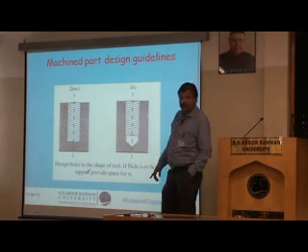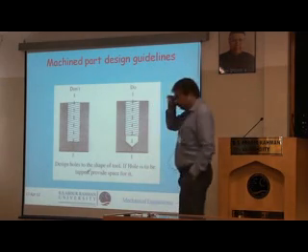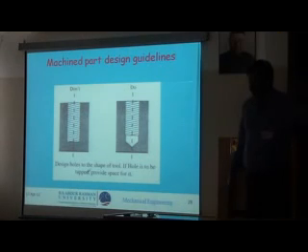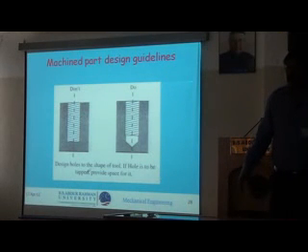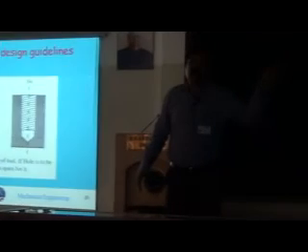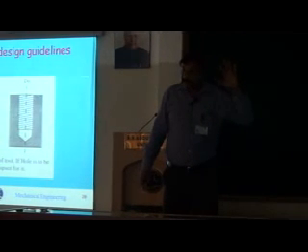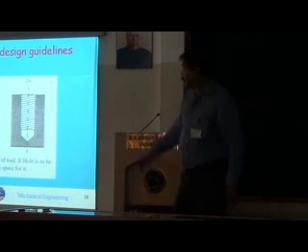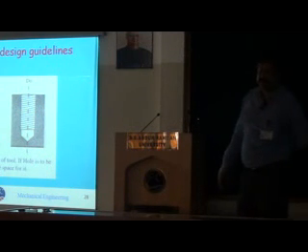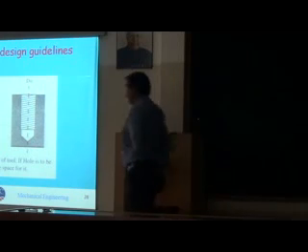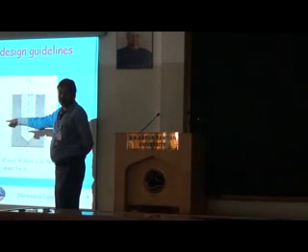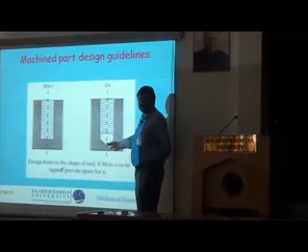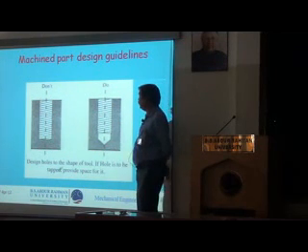This is a blind hole. So this is for designing components by machining. Earlier I have talked about injection molding. Injection molding is mainly for plastic parts. Then I have talked about sheet metal parts. Then I have talked about casting. Now I am talking about metal cutting. Now a blind hole with a flat bottom is very difficult to make because your drill bit always leaves a conical surface like this. So if it is acceptable, the designer must provide scope for this. Next slide.